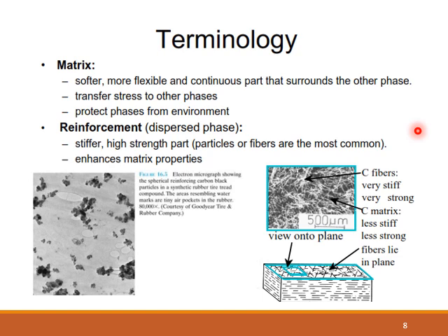In understanding composite material, you must understand what makes up a composite material. Since we are talking about a combination of materials in the design of the composite, there must be a matrix and a reinforcing phase. The phases are distinct: one of them is going to be the matrix phase, and the other will be the reinforcing phase. And this is important because these phases will have different roles to play in the eventual property of the composite material.